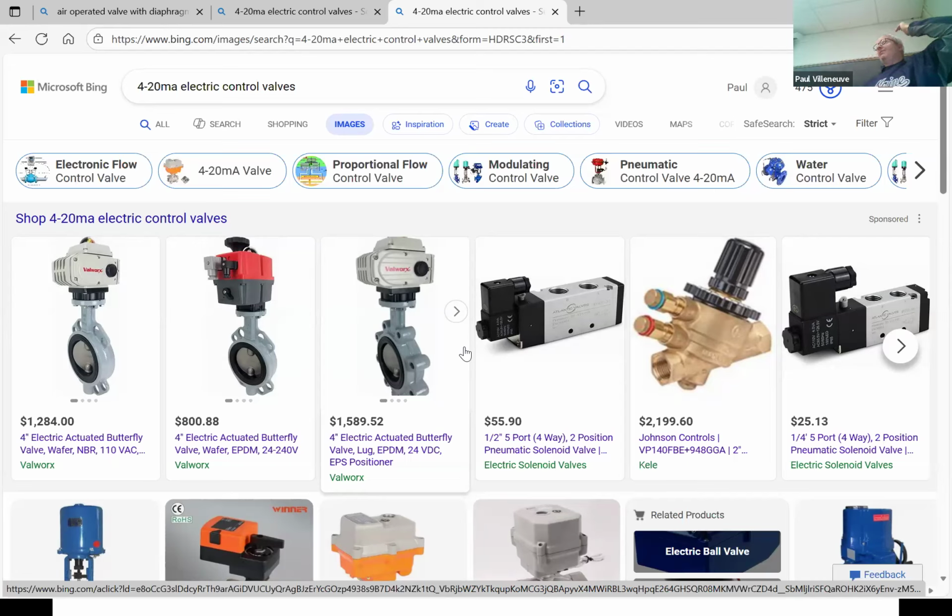Maybe, but the 4 to 20 milliamps is really small cable. It's fancy cable, it's shielded, twisted shielded pair, so you have no noise, but it's pretty fancy stuff. I think that's the bulk of the concern with wireless: if it's in an electrically noisy environment, the radio frequency could get degraded. It is, but what's the nice thing about digital, right? There's always a packet with a bit or a bunch of bits at the end or the beginning telling you what you should expect. And if you think you missed a bit, it'll give you an error. So there's a lot of built-in error checking with computer stuff that you don't even realize is happening.